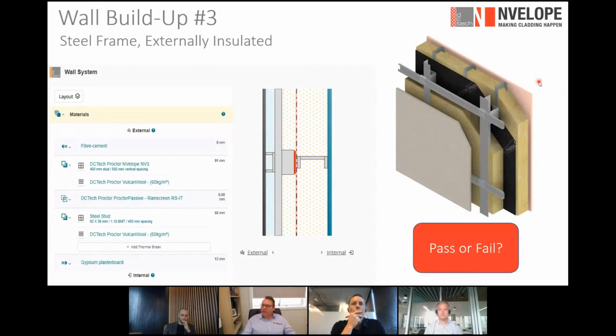So this wall build-up, starting from the inside, again, our plasterboard, and you have your typical 90mm stud insulation, vapor permeable membrane, of course, but we've now added a cantilever system, like a helping hand system, like our envelope. This is our NV3. What it's doing is producing a cavity large enough for us to install continuous insulation. It creates a ventilated pathway for air to run through for drying potential. And we've also allowed for mechanical fixings and the cladding itself.